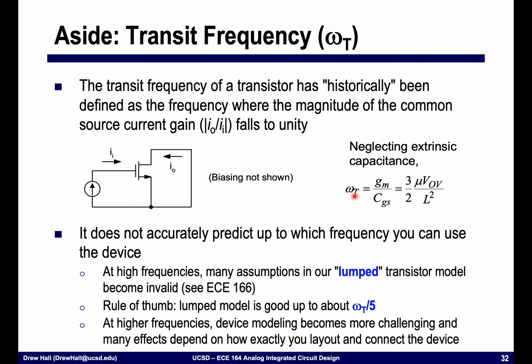And the capacitance that we're describing here is a lumped model where the capacitance is all taken at the input, CGS, whereas really if you were to draw it out, it's distributed. Along the drain to source channel, there's a bunch of really small capacitors that in total add up to CGS, but you would not be able to treat them as a simple lumped model.